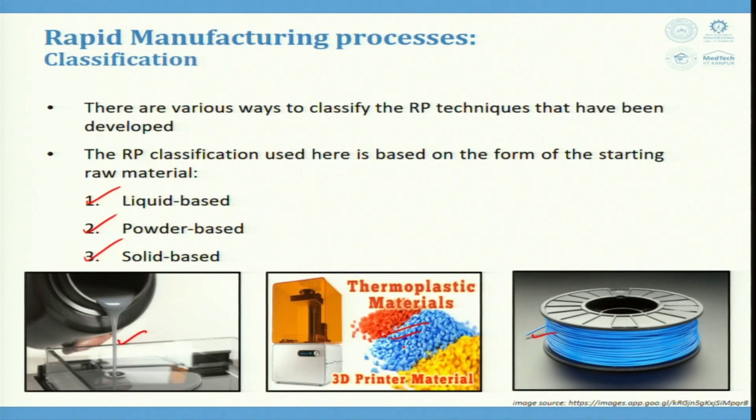We will try to see how we use all these types of materials and try to classify the rapid prototyping processes. So, when I talk about liquid based types, it has further types, maybe inkjet or photopolymerization types of rapid prototyping technologies. Inkjet includes multi-jet modeling, drop on demand inkjet or so, and photopolymerization includes the UV, that is PolyJet technologies or